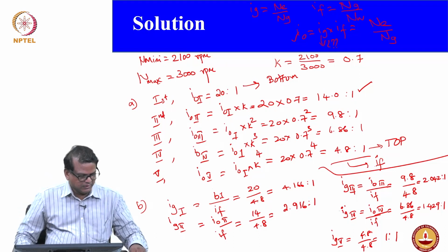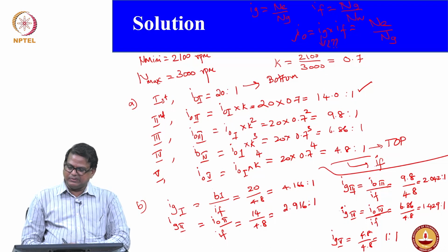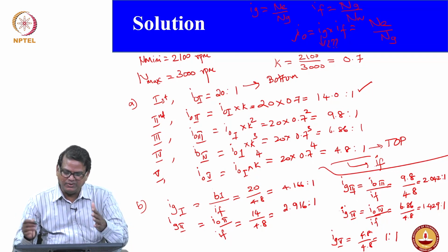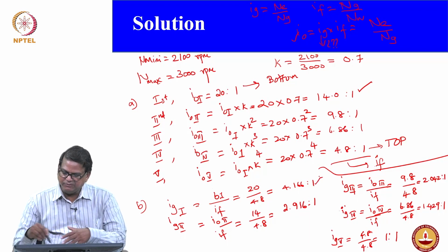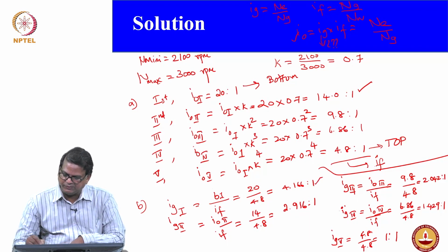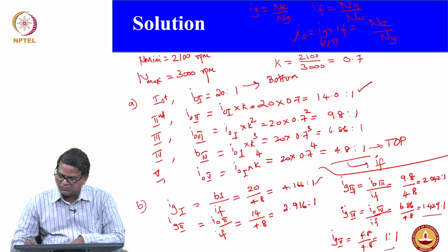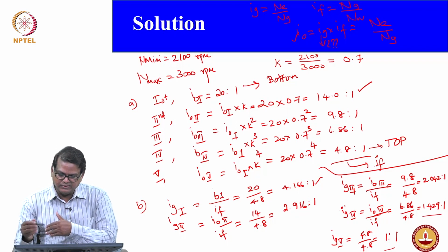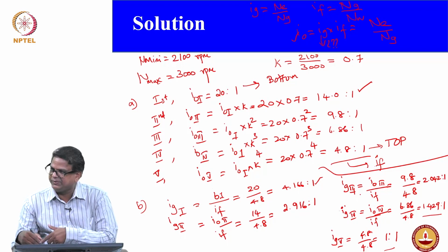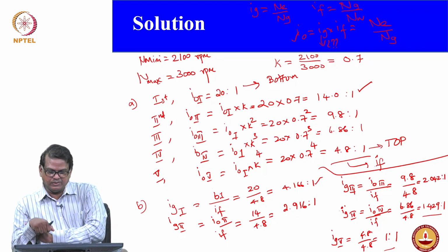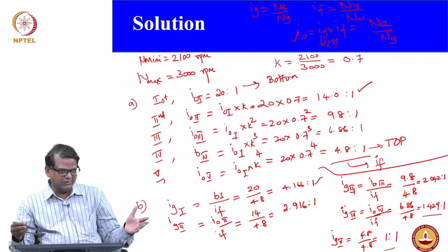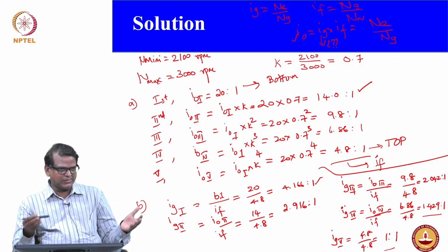This is good. Can you look very closely? This is the wide range, right? First gear has a very high gear reduction, 4.166. And if you look at the higher speeds, between 4th and 5th, this is 1.429 and this is 1. Very close range compared to your second and third, right? 4th and 5th gears are very close range. And as said in the earlier slides, first gear should have high gradability. The moment you have high gradability, the reduction will be very large.